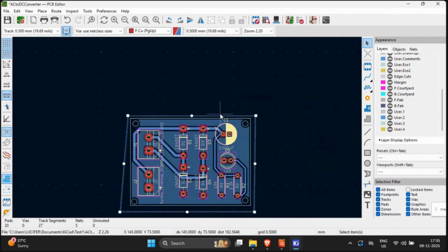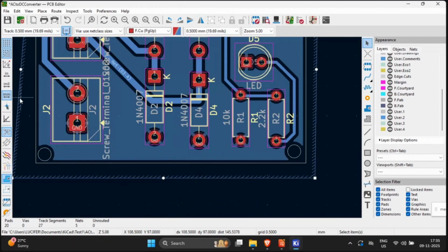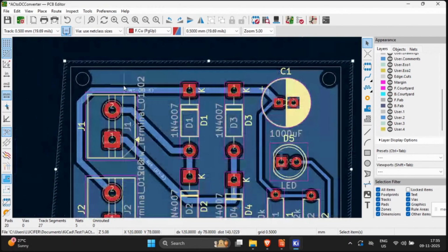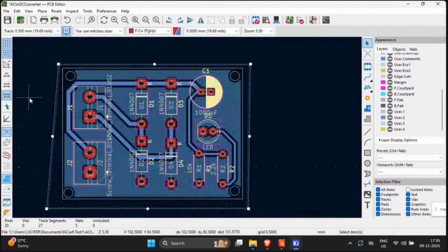Oh yeah, sorry. I really forgot to mention we have to press the button B. My bad. So after selecting the copper area tool, we just have to define it as ground terminal as we did. In the end, we just have to press B. Apologies from my end. So yeah, as you can see, only the traces you can see here, they are insulated. You can see these layers are removed and they work as normal wiring. And yeah, that's where you have it.